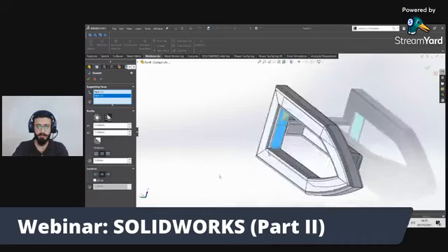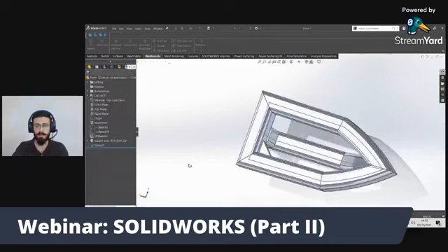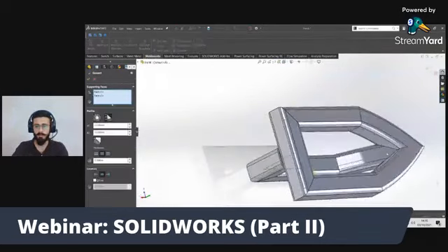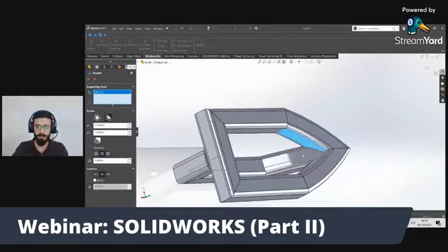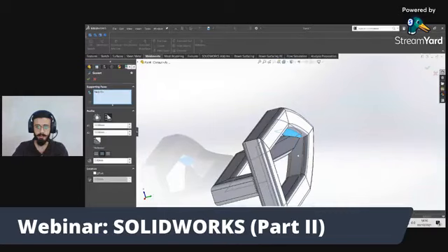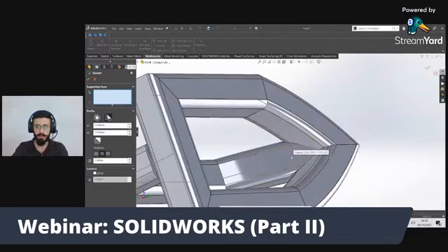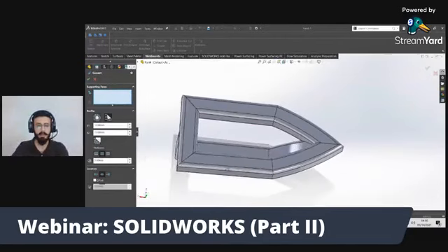And now from a face here also, you can add anywhere. Let's add it in the front. We want to add it here, here and here. It's not possible because there is a new body down there. Just do it here. Now you can add it only between two perpendicular faces.